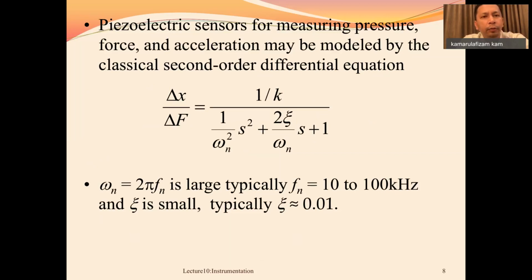It is also important because you need to know the application that you want to use. The piezo sensors actually depend on the application that you want to use. The design of the sensor is depending on the application. Some applications require high frequency vibration or motion, and in some applications the vibration or motion is very small. So this frequency basically defines the construction and the selection of piezo sensors.